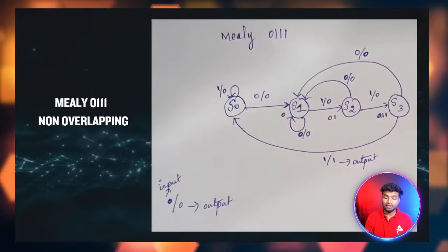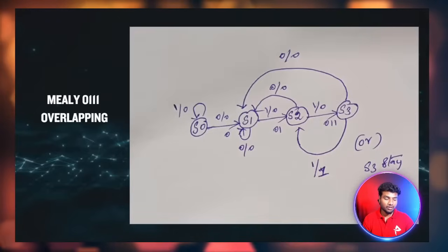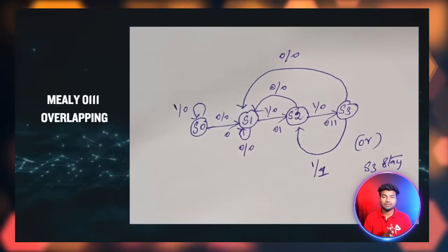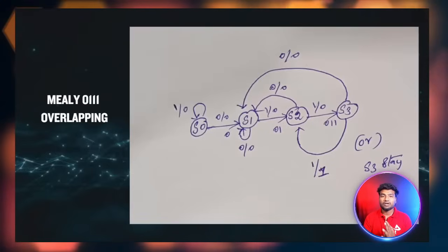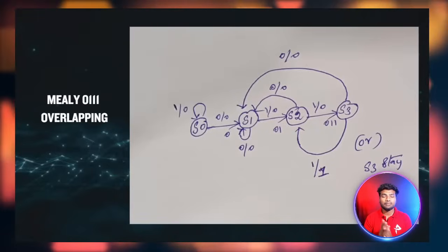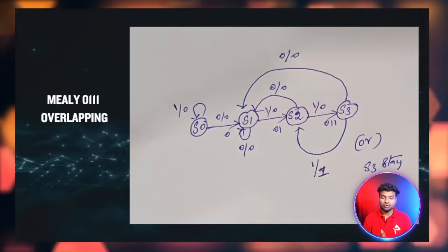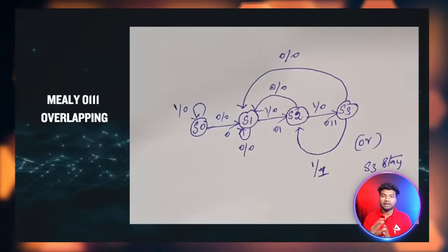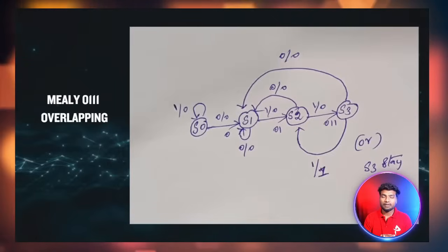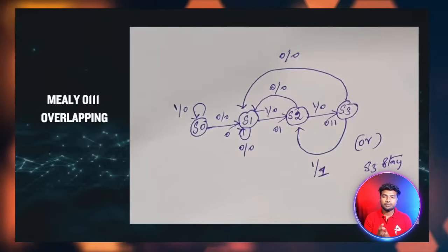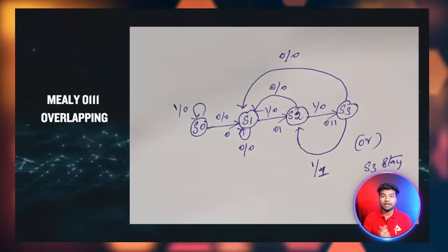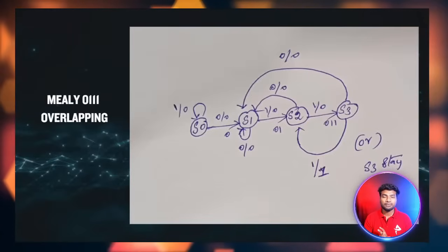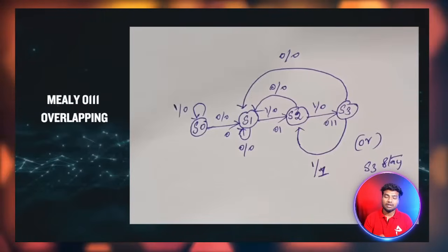This is very important. When you write Verilog code, you have to write FSM code for all the logic. If you take the UART protocol, all protocols are based on FSM logic only. So you must be aware of FSM concepts: Mealy type, Moore type, state transition. The main thing is that in a Moore machine the output is based on the current state only, but in a Mealy machine the output is based on the current input and also the current state.